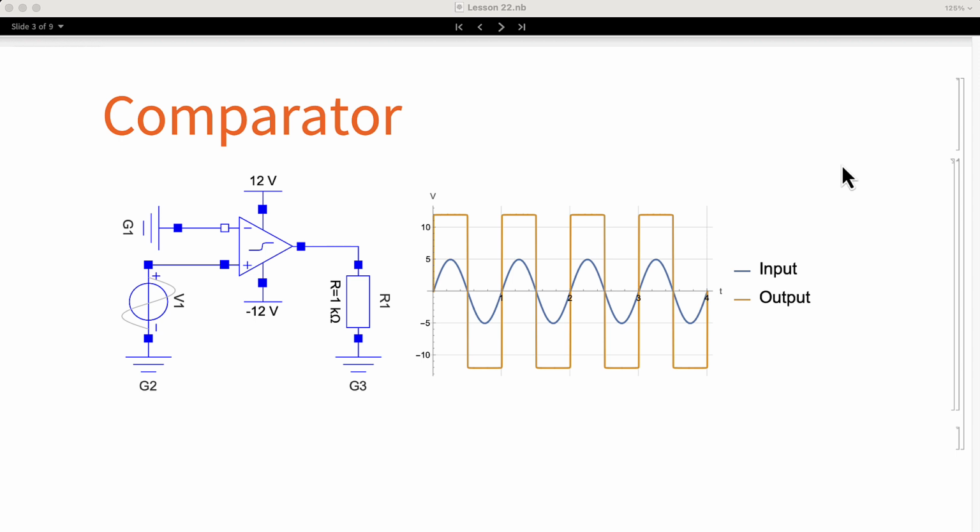Additionally, the change from positive to negative voltage at the output is limited by the slew rate. If this is an issue, there exist special op-amps that are enhanced to be used as comparators. Those present less offset and faster slew rate. Additionally, they can be used in cases where we don't want output as large as the power supply.